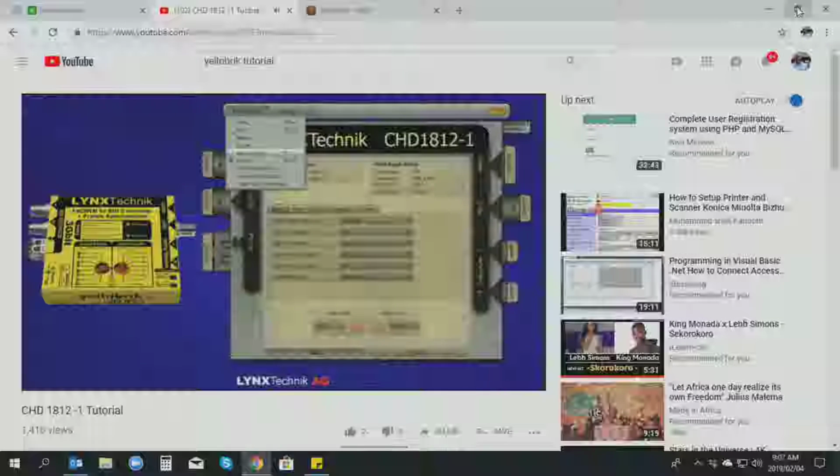Factory reset, an extremely important function for me because I often mess things up. Click on that and that will reset all the internal values to factory default. If you haven't got access to the yellow GUI, there's a mechanical switch between the power connector and the fiber connector on this side of the module. You'll see a little silver Phillips screw, and underneath that is a tiny hole, and you stick a paper clip in there, click on that, and that'll do a factory reset of the module, obviously when the power's applied, without needing to have the software running. So again, there's a physical factory reset on the module, as well as a software factory reset.